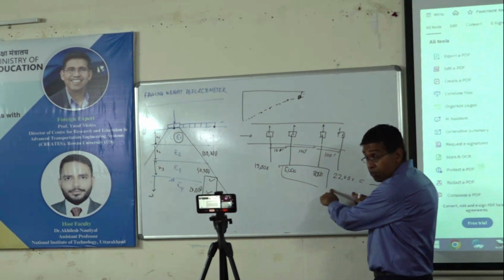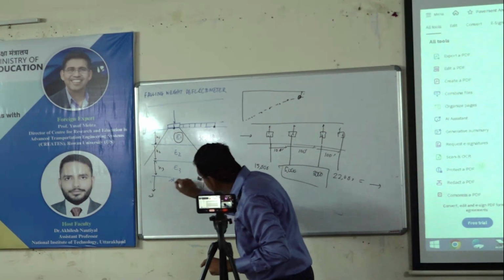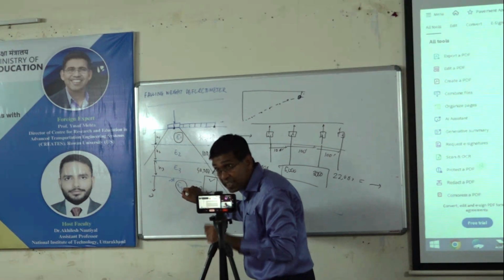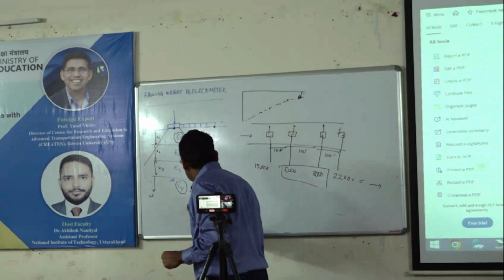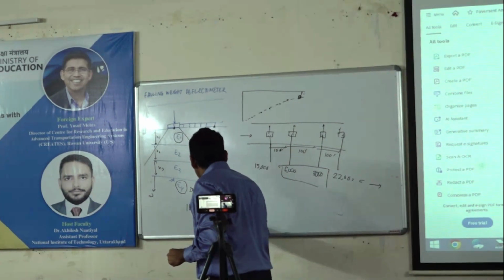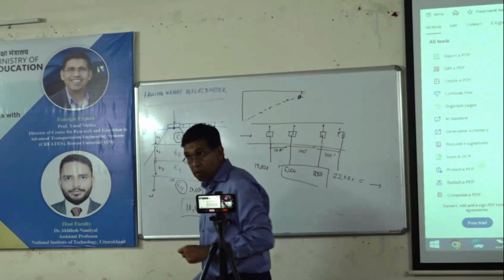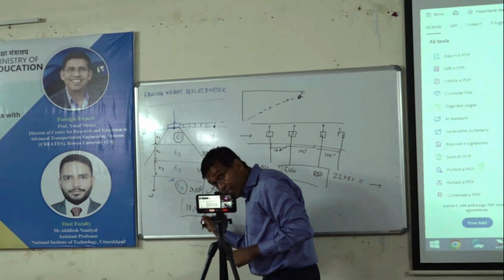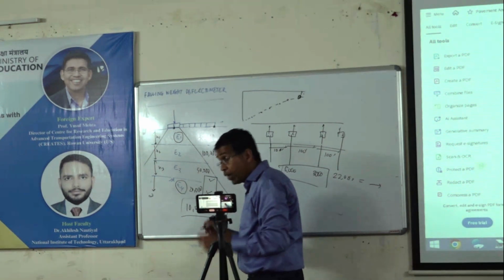And not only that, if you know the classification of this subgrade or any historical data of this subgrade which tells you, okay, the range of values are between 10,000 and 25,000, let's say, you need to have an independent check of this 10,000 to 25,000. Okay, I cannot have 5,000 and 3,000.